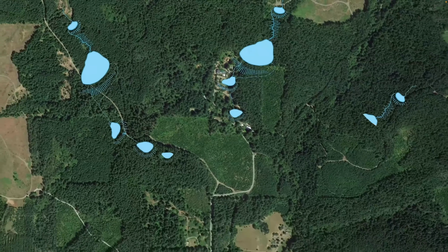It's also possible, and sometimes a very good choice, especially for larger ponds, to have a geotechnical analysis done by a professional, and they may even put down a series of boreholes. So there's really a scale of decision making around how much technical analysis you do. But if you're building ponds that need to be engineered, and there are often requirements with water resources departments at a certain scale at which the ponds need to be engineered, a full professional geotechnical analysis may be called for. When you dig the test pit, you'll be looking for a few things.